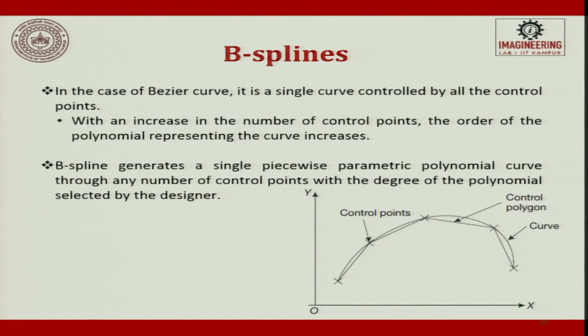So, the next curve which we saw was B-spline. I have said the limitation of Bezier curve also. What is the limitation of Bezier curve? If you try to move one point, the complete curve profile changes, which you do not want. So, if you want to have a very complex curve, you have to have so many start points, end points, so many control points in between, such that you can try to draw a complex object. But this puts a restriction on me.